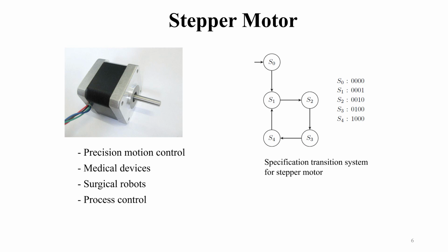Stepper motor has 4 or 6 leads on which a sequence of values like 0001, 0010, 0100, 1000, 0001 causes the motor to rotate. Every time we switch to the next value in the sequence, the motor rotates by a small angle. For example, when we switch from 0001 to 0010, the motor rotates, and then from 0010 to 0100 again, it rotates, and so on. By giving this repeated sequence continuously, the motor rotates. Hence, this behavior can be achieved by using a microcontroller to control the motor.